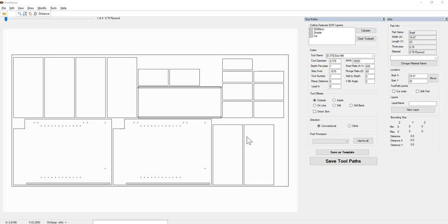Cutting on a CNC with the vacuum, you want to be able to preserve as much of the surface area as possible without cutting all the way through, or you want to cut your biggest parts last, or cut your smallest parts first. We're going to take a look at how we could arrange in Cabinet Parts Pro to cut the smaller parts first. The item that we're going to take a look at here is on the Info tab